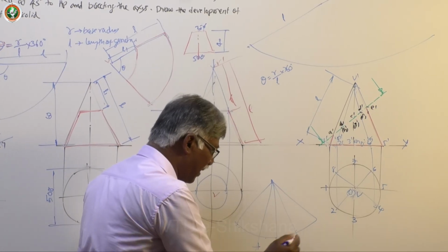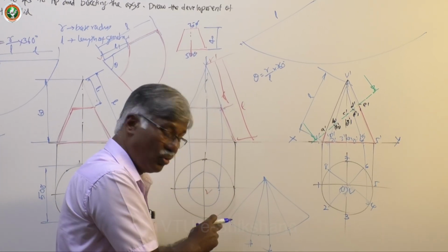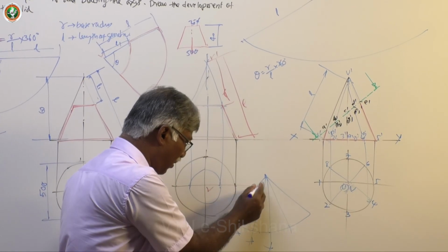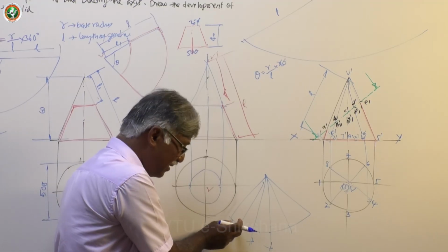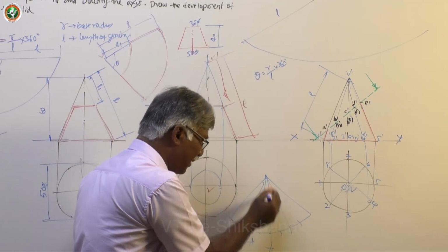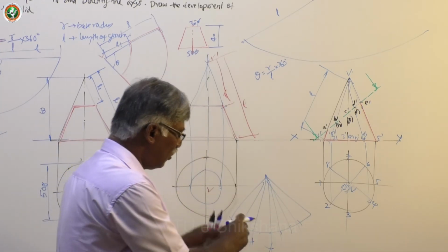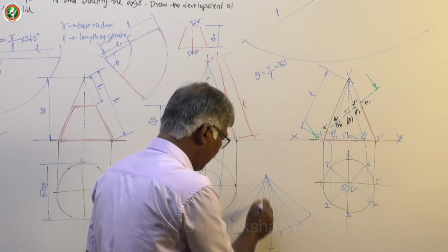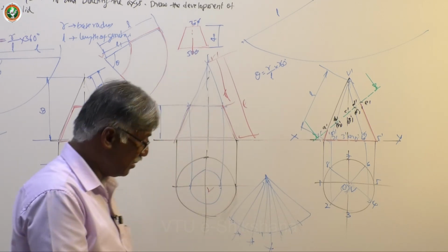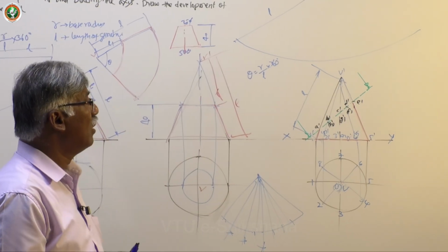Isn't it? Again do that. Again you have to make this into 2. Again take more than half of this and draw. So you will get 1/8 here. You mark here. Mark here. Say you got 1, 2, 3, 4, 5, 6, 7, 8. Like that. So yeah, this I have to make. So 8 divisions you get. So by arc method you can do.